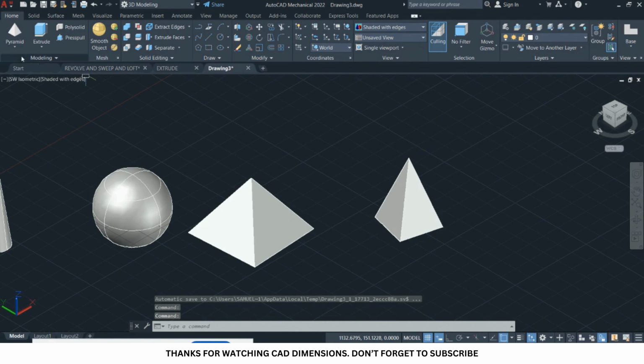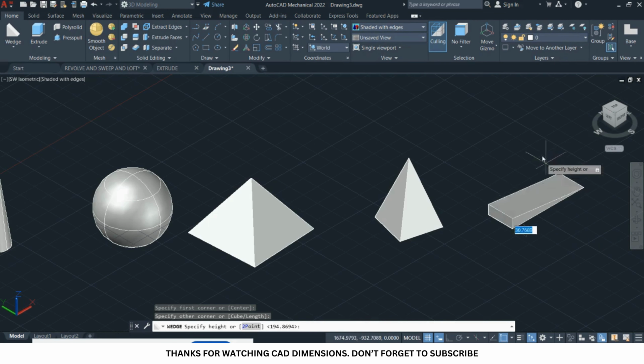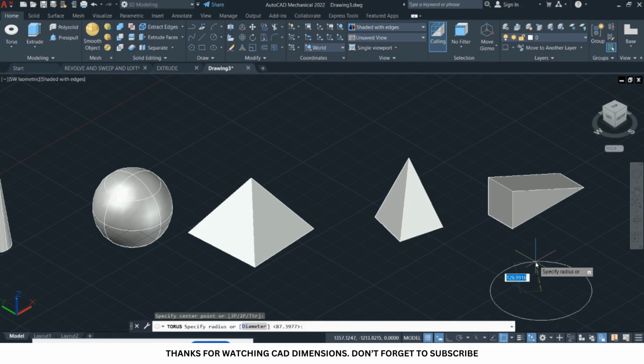Okay, then we have the wedge. So you also specify a base point, you draw the wedge, all right, and then you raise the height of the wedge. Okay, so you just have to be playing around with it. And the last one is a torus, which is also quite an interesting solid primitive. It's mostly a circle, or looks like a donut shape, right? So you specify the circle.